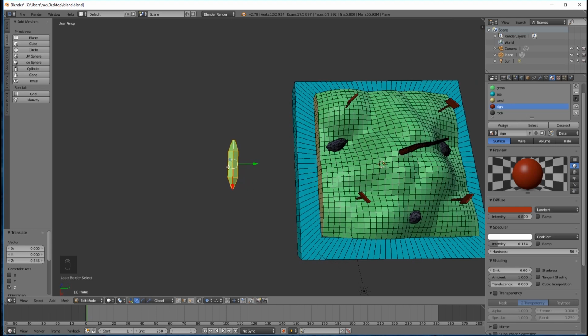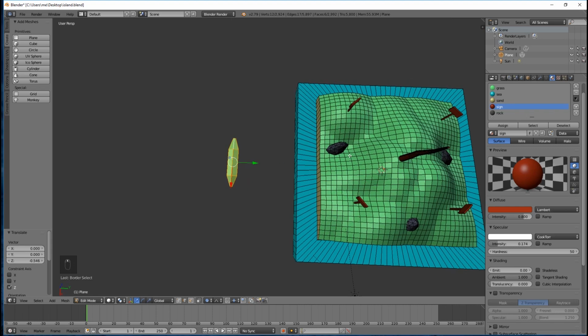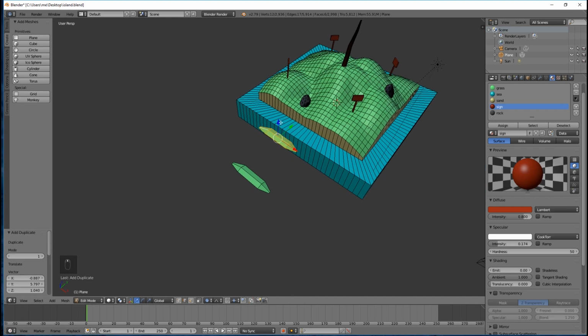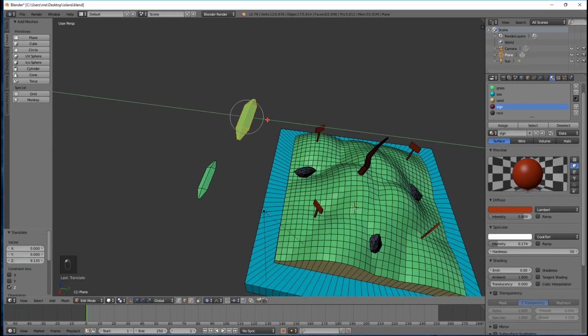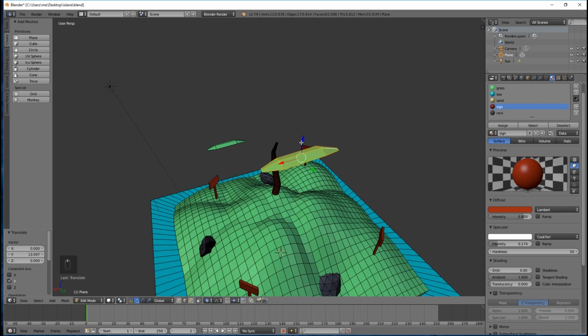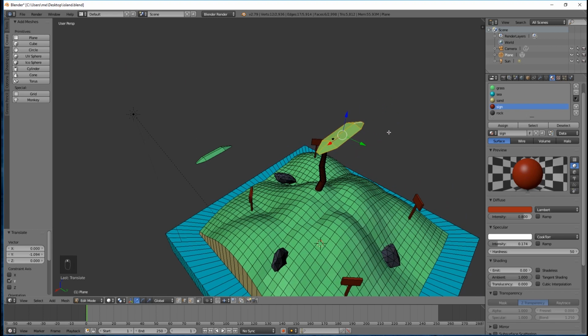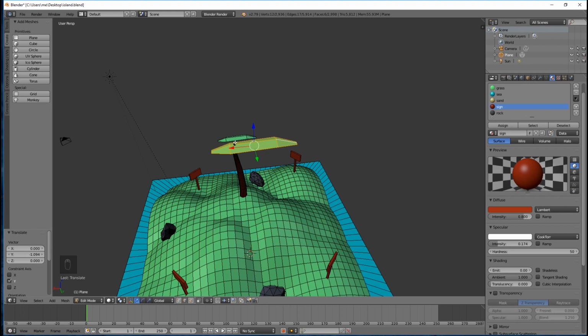Right, so I'm not going to move this palm leaf off and over to here, because we're going to need quite a few leaves. And I don't want there to be any risk of that. So I'm going to keep this one here and just press Shift D to duplicate it. And it's this copy of a leaf which I'm going to move into position. So I'm going to move that up. And this can get a little bit fiddly, I guess, just moving it into position. And also thinking about scale, because I just realized I've still got proportional editing on. Let's just switch that off, because that is starting to affect a few things. So do make sure the proportional editing is off once you've finished making the leaf.